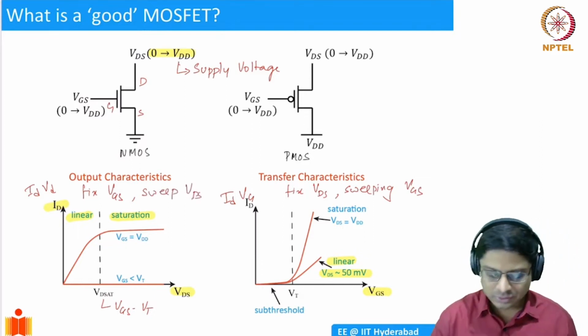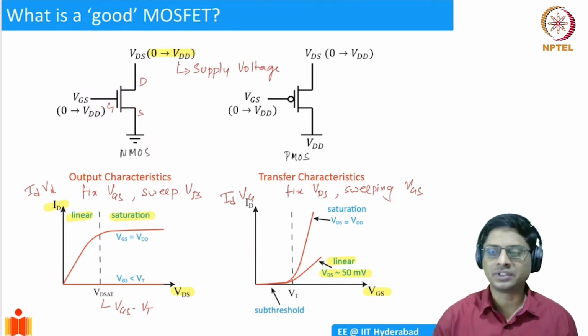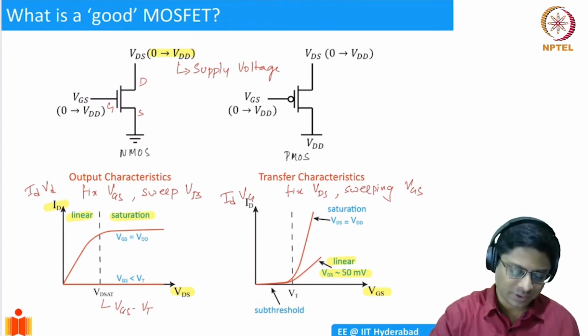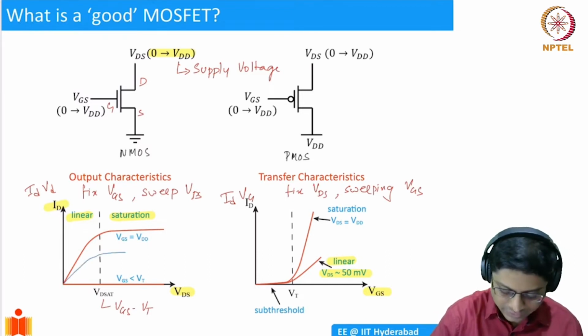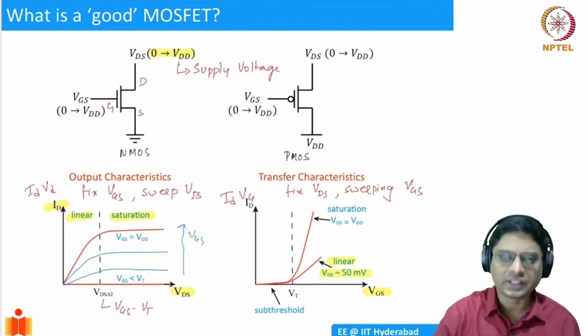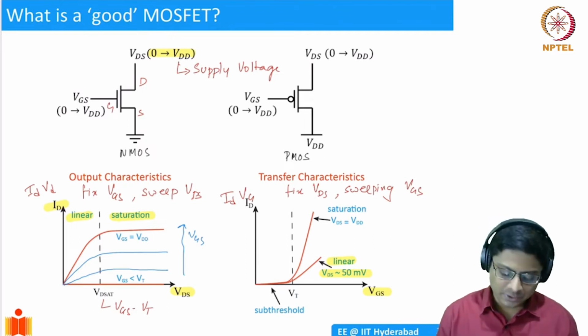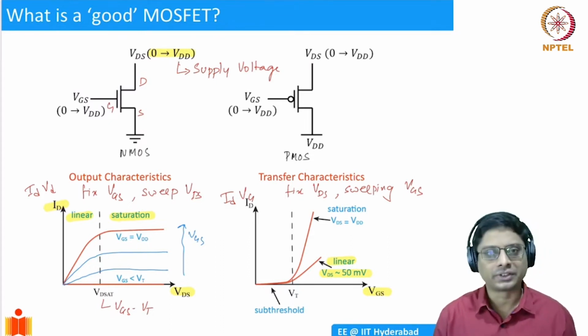Okay. So these characteristics, you can actually do the measurements at multiple VGSs or VDSs. So then you get a family of curves, like what we have seen in the last lecture. We showed you that there will be a quadratic relation like this, right? Drain current is going to increase as your gate voltage increases, and there's a quadratic behavior in the saturation. That's what we said. Okay, we get a family of curves. So this is for an NMOS device.